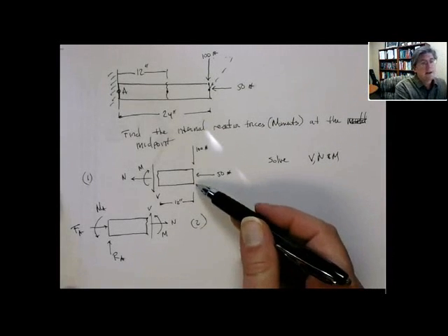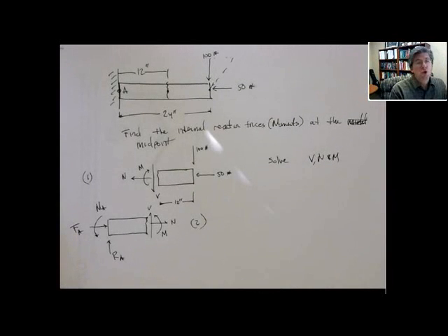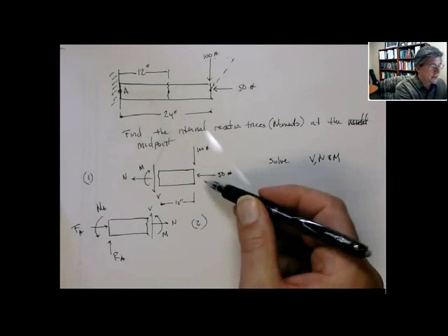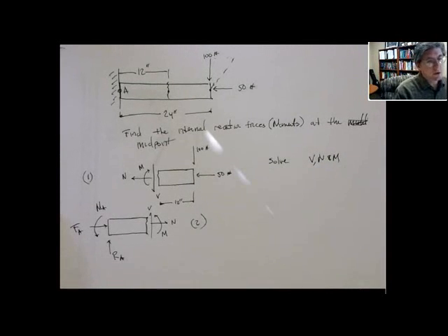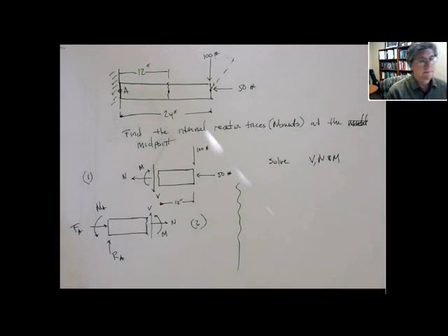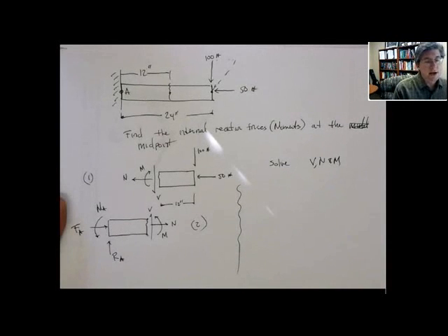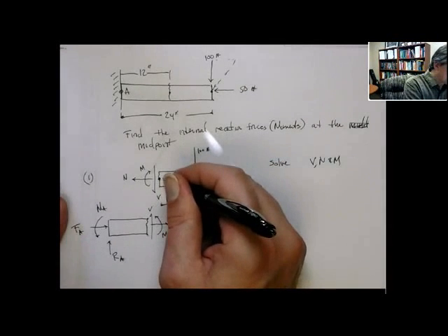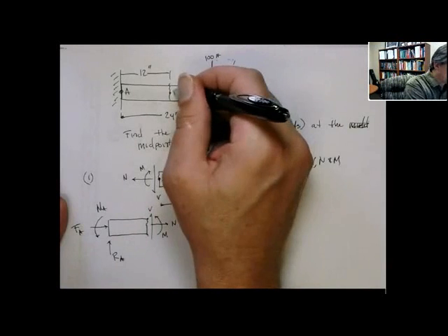This situation, and the approach is the same way. Okay, you use sum of forces and sum of moments to solve for V, N, and M on each free body diagram. All right. So you want to take care in carefully drawing this. So if we look at the first free body diagram, okay, we can directly write sum of forces in the x, sum of forces in y, and sum of moments around. Well, let's pick this point. Call this point D, right?